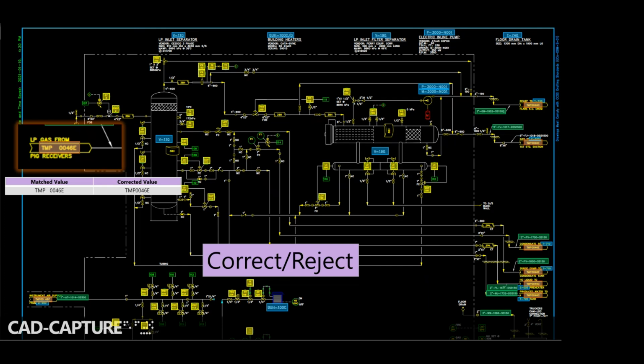so we can identify near misses. Here's an example where a space is left in a continuation tag. On the left-hand side, you see what's been typed in. On the right, you can see the actual value as it should be if it had been entered correctly. We can identify these because we can adjust the patterns to take account of common errors. So this could be dashes, spaces, leading zeros, a host of different things that may have been entered incorrectly, but ultimately can lead us to still identify the tag.